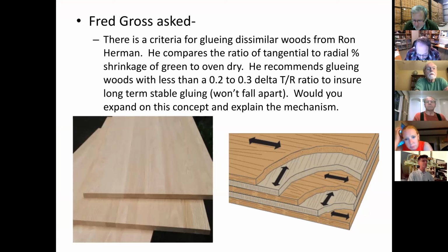Generally speaking, if I'm gluing planks together, I don't care. And why do I say that? Think about plywood. If I'm edge gluing pieces together to make panels, I'm never going to have the stresses in those panels, regardless between radial and tangential, that I would have in a piece of plywood.